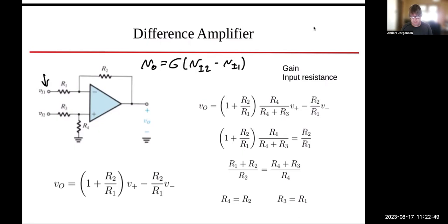In that case, we have effectively a non-inverting amplifier, except that we have a voltage divider on the input. So the voltage seen on the input right here is actually a voltage division between R3 and R4. But other than that, it gets multiplied by the gain that comes out of a non-inverting amplifier with R2 and R1. So that's what we have over here on the first part.